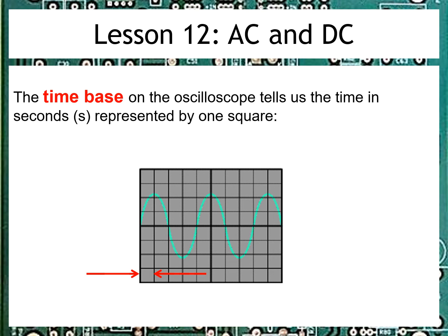When I'm using the oscilloscope in the lab, I have something on there called the time base. And usually when I'm fiddling around with this, I'm trying to make sure that you've got a nice clear image with a wave sitting squarely on the screen, rather like the one in the diagram below. But in reality, the time base is there to set a scale. So it will tell me how much time each square along that scale represents.